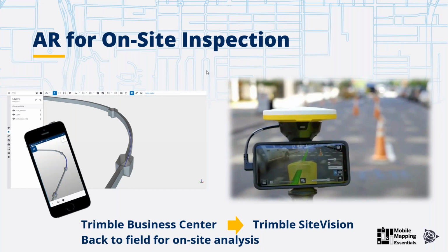Okay, so the Trimble MX7 is a mobile mapping technology, which in general we present as mapping grade accuracy. What does it mean? Well, the performance of these absolute accuracies is mainly the consequence of the kind of IMU, or inertial platform, we have in the system, and the GNSS conditions the specific MX7 has at that moment during the mission.